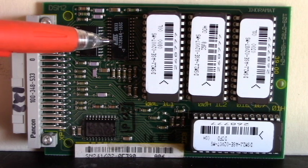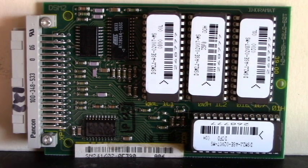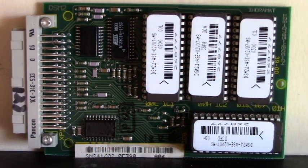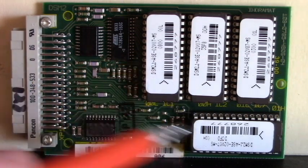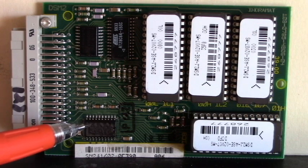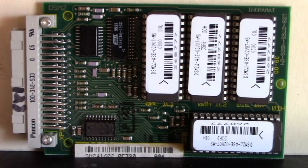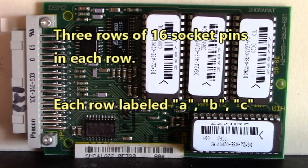The AT28C64 resides on the low byte side. There's two EPROMs over here that reside on the low byte side, and there's two EPROMs that reside on the high byte side. And this 74HCT245 controls the direction of the data to the high byte side. Here's the connector that connects to our programming adapter. Now let's go look at my drawings.